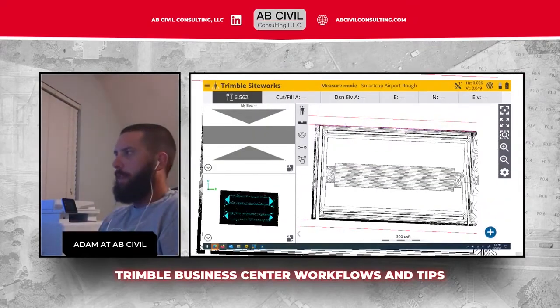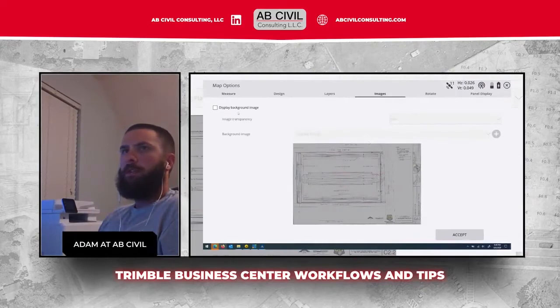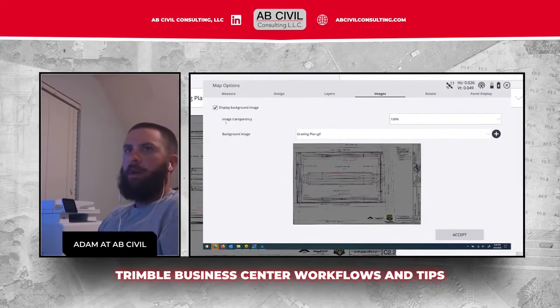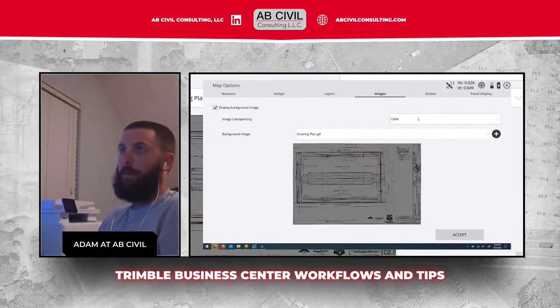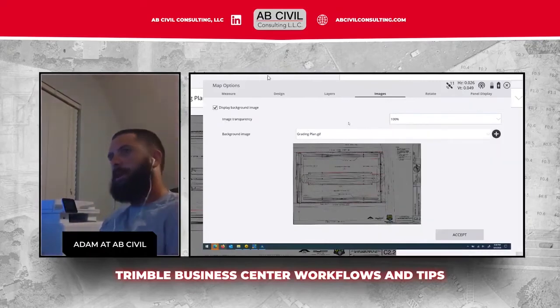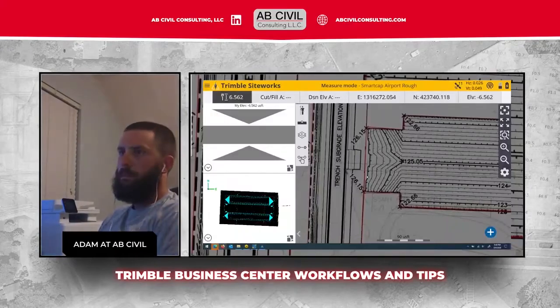So again, we've got the background image in the folder. Hit your settings, images, display background image. I always pick 100%. It says image transparency. I don't know if anyone at Trimble knows they got it backwards. This is not 100% transparency, 0% transparency, I think. Grading plan, hit accept. And there's that image. You can see the contour lines, how they've lined up.